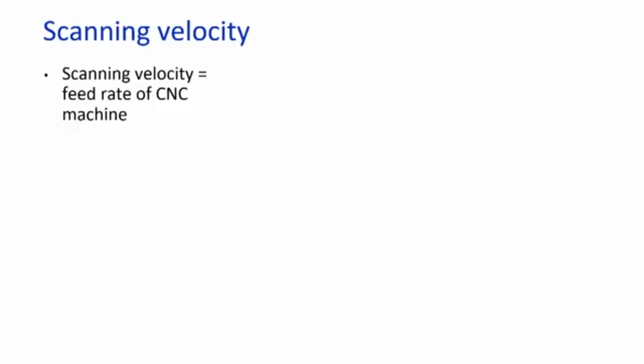So, it is non-linear, the laser power is non-linearly acting upon the bend angle. Therefore, it is very essential that we are very careful in choosing the laser power during the laser bending operation. Now, let us see the effect of scan velocity or scanning velocity. Scanning velocity is also called the feed rate of the CNC machine.